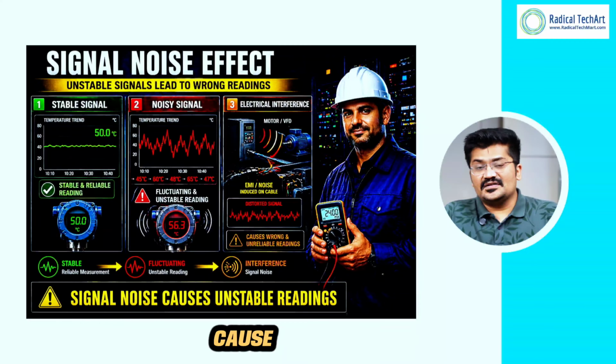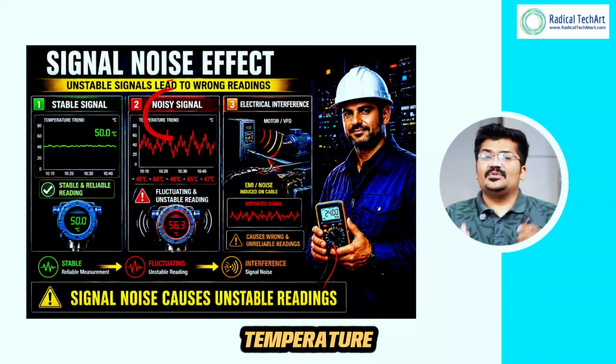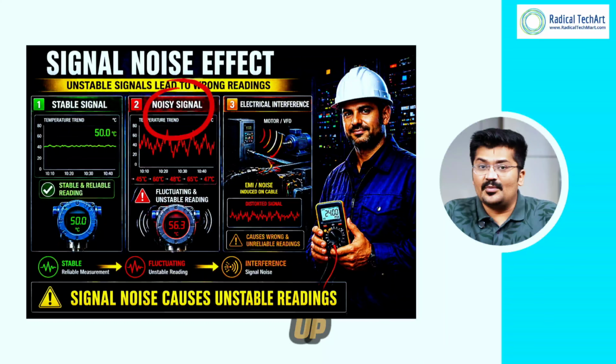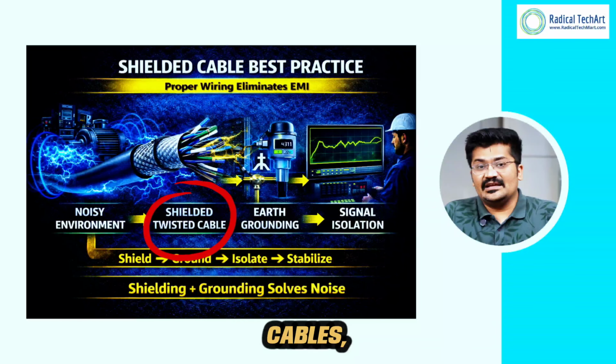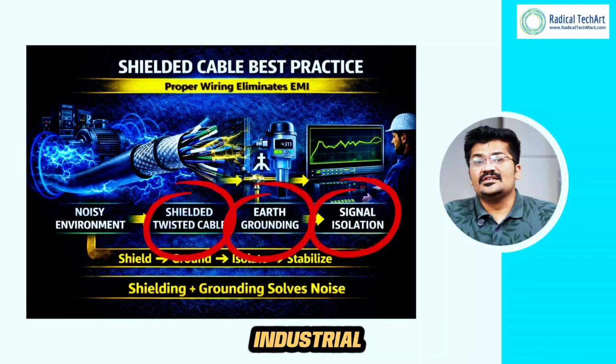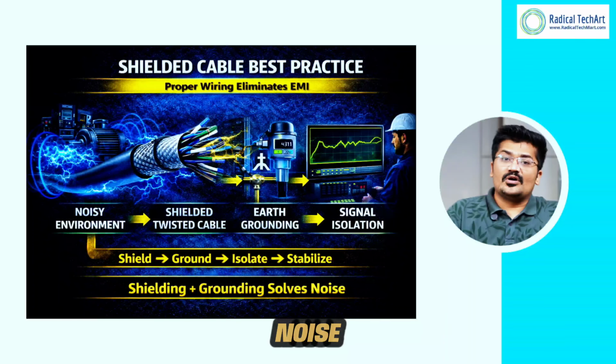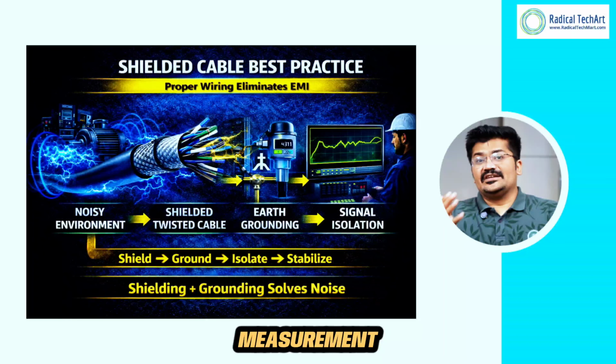Signal noise can cause unstable or fluctuating readings. For example, a temperature signal that jumps rapidly up and down. To reduce signal noise, engineers may use shielded cables, proper grounding, signal isolation, and industrial transmitters designed for noisy environments. Understanding signal noise helps engineers improve measurement reliability.